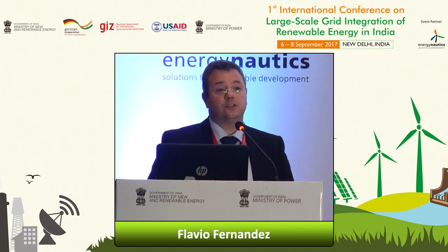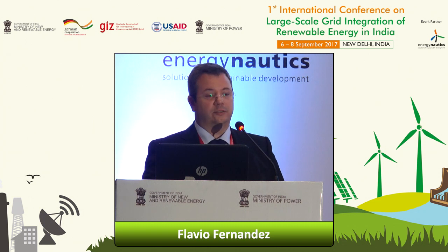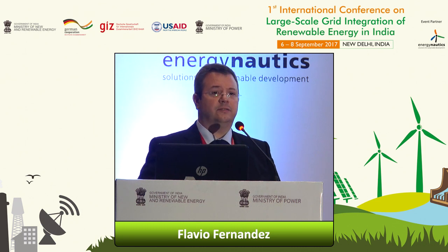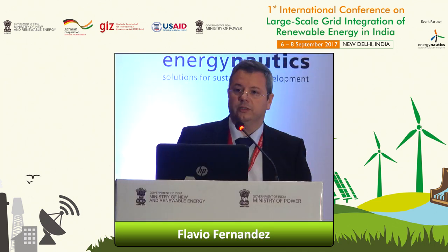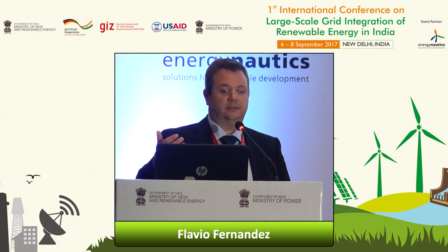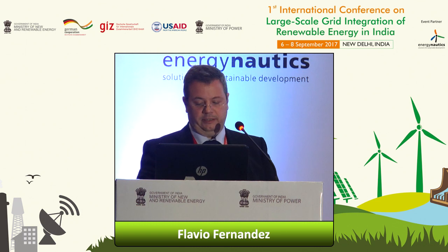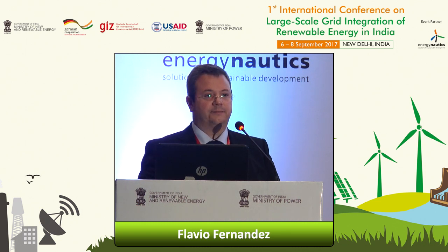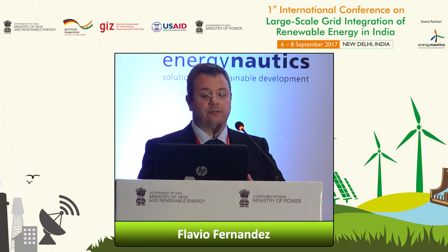For that kind of representation, we can aggregate the model, so we don't need to go for all the internal representation of the internal components. Basically, you include the equations in your dynamic control, and then you only need, in terms of network interfaces, one component, which is at the end either a current source or a voltage source as an interface to the network. In our case, we have a so-called static generator, as we call it, to represent whatever generation is connected through a converter.